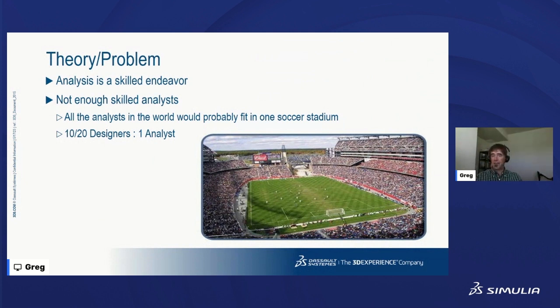You can do this as a design verification, validation tool. Maybe just make some simple changes to the model, see how it performs. Is it going to deflect more? Do I change where my stresses are? Of course, we want to know if our parts are going to break, but sometimes we can just use it as a simple design tool to find out where our high stresses are, or how it's going to displace. Something as simple as putting a unit load of 1 on a model. Even if I don't know what the load is, if I just put a unit load of 1 on there, I may not know what the real stresses are, but I have an idea how that product is going to behave under proper loading.